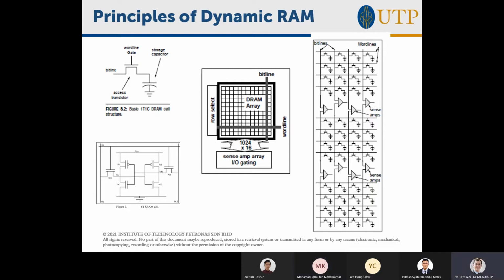Okay, great. Now it's going to get very complicated very quickly. Given that the way we access this is that we have to turn on the word line and the correct bit line we have to choose, and then there's this sense amplifier magic that's actually reading a small value of charge.